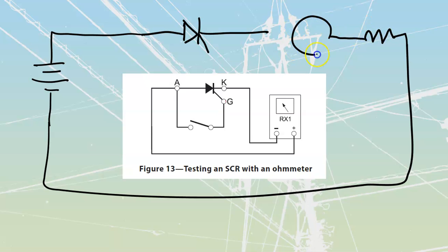And then I'm just going to stick my ammeter in. I'm going to hook it onto the two leads of my meter, the red and the black, so that I am connected to the ammeter. This is my red lead. This is going to be my black lead. And I'm going to use my meter as the ammeter, rather than trying to deliver the current out of the meter, which isn't going to work. I'm going to deliver it out of just a C-cell battery.